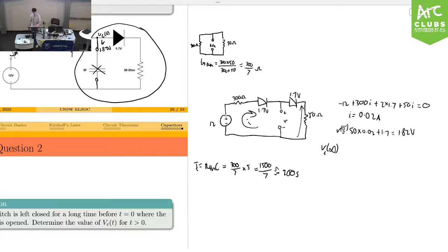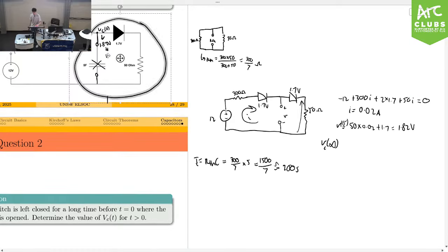What that tells you is that you've got 1.87 volts here. Naturally, if you have no source connected to that 1.87 volts, then it's slowly going to decay to 0 volts. However, once that 1.87 volts gets down to 1.7, let's just say after some time, then there's going to be no net current going through the diode. So it reverse biases and then becomes an open circuit.